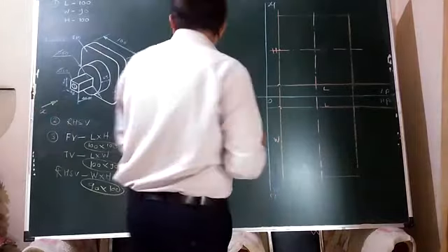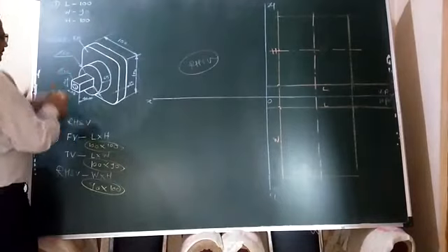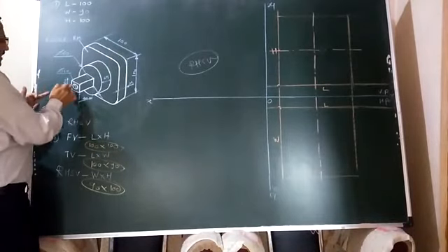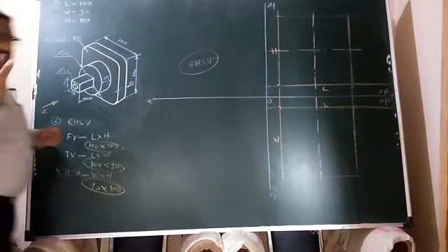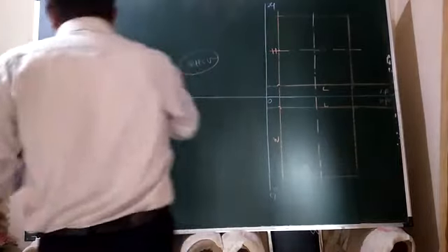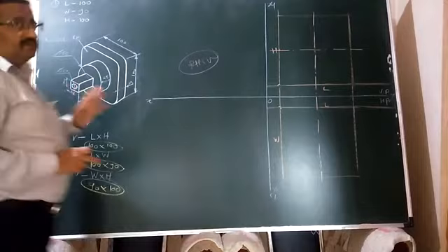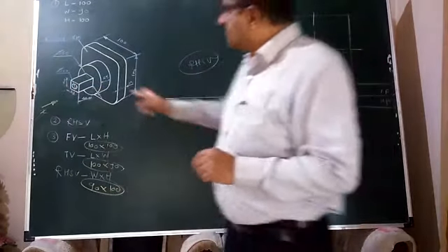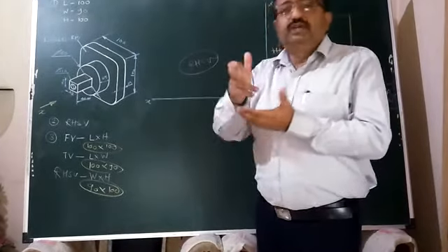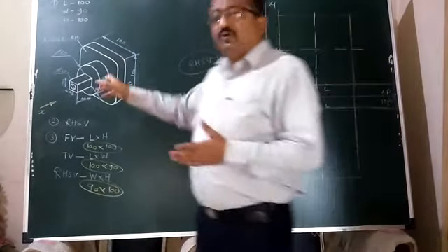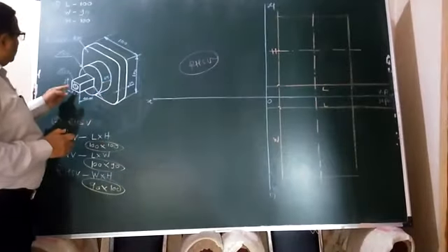Now see, what do we have to do? We have to fit the plate here, and centrally we should start with the center. Centrally one hole is provided, that is a through hole. The diameter of the hole is 10 and it is cut in this way, width wise through the entire object. When its depth is not mentioned in case of a hole, one should consider that such a hole is cut through. A through drill has been produced in that object, meaning the entire object has been drilled through. So depth is not mentioned.